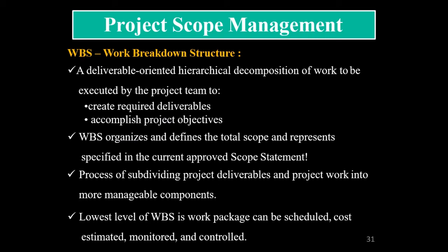Work breakdown structure is dividing the work into different parts. For example, building a house. If I divide it as excavation, construction of plinth, then column, then comes your slab. If I divide this into smaller parts, what will happen? Defining the time, labor and resources required will be easier. So in this way, work breakdown structure helps to do efficient work.